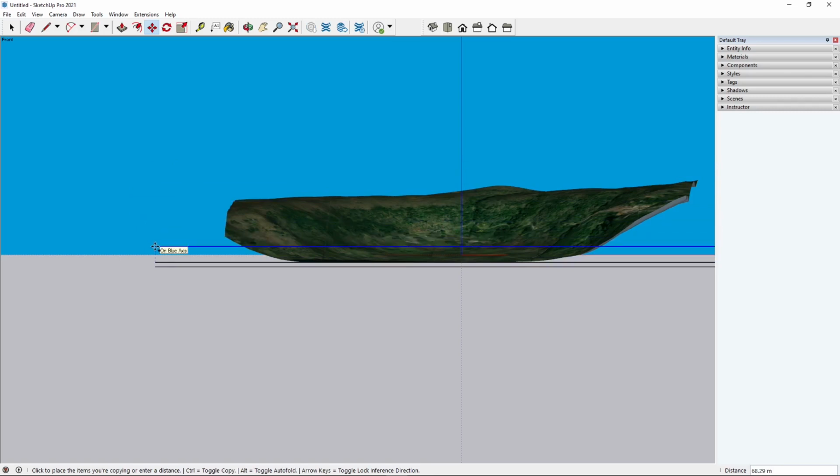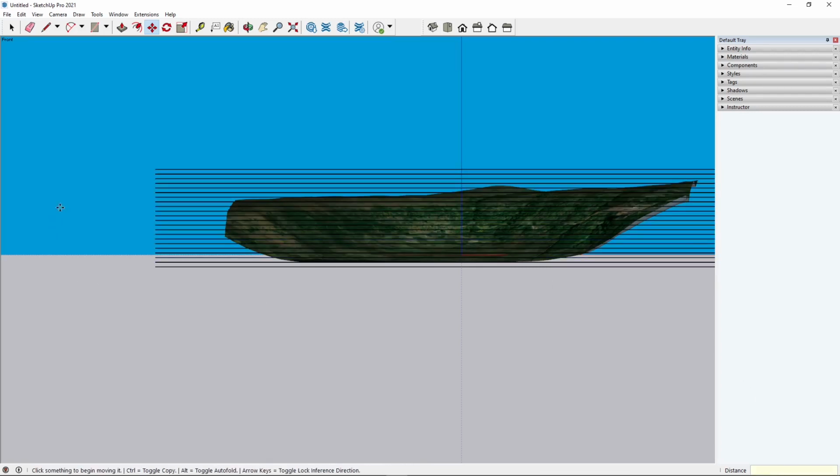Again, type 20 to define the distance between the first one and the second one, and then without touching anything, just type, for example, let's say 20, and then type X or the times. Press enter, and then you will find the copies.